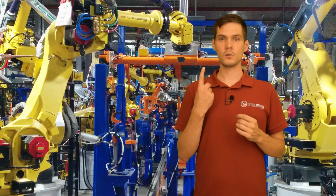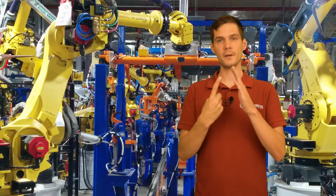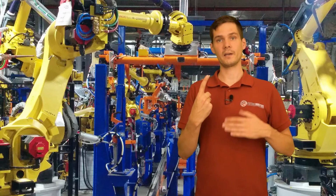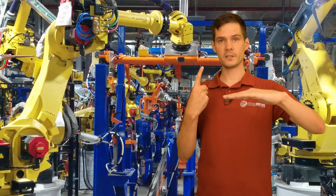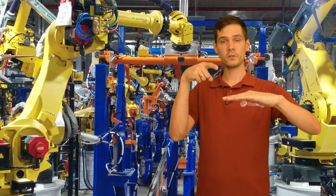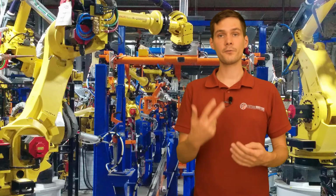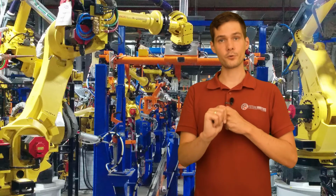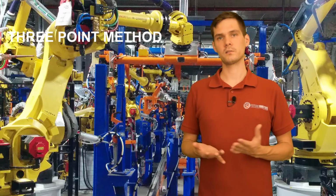Okay, so like in my video, I'm going to use a finger as my tool frame. So imagine that's my TCP, and I taught it and it's pretty accurate. And right now what you're going to do, you're going to take that finger and point it onto 3 points that are going to define the plane. Because there are 3 ways you can teach your user frame. Number 1 is the 3-point method, and that's the most commonly used. I would say that's the one that everybody is using.